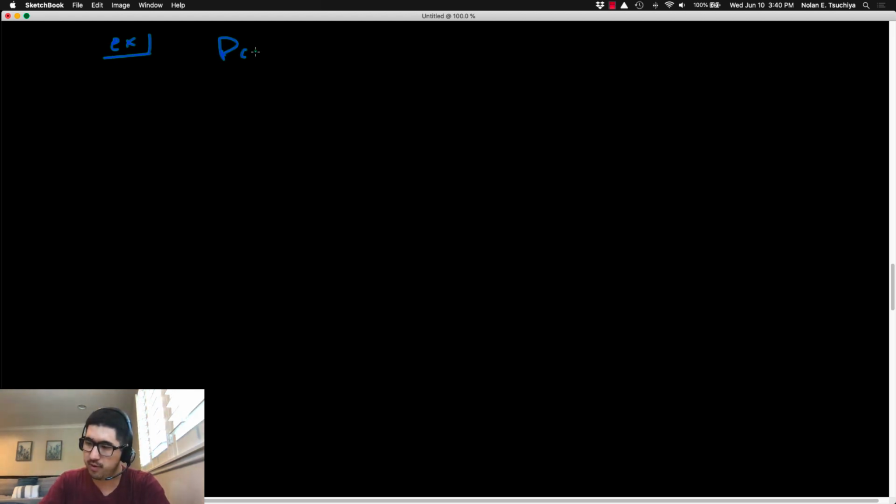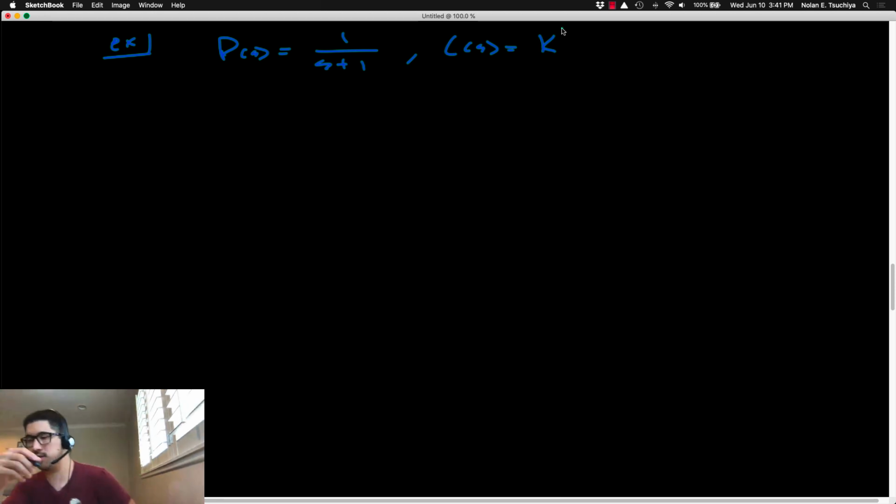For this example, we have a simple first order plant and a simple proportional controller. Proportional controller, gain controller, constant value controller, those are all saying the same thing. Basically that the transfer function itself for the controller, C of S, is just a constant value. It's just a scalar constant. So C of S has no poles, no zeros, it's just a gain.